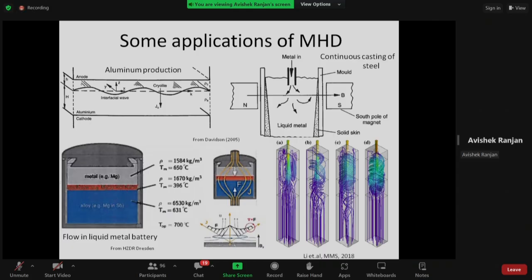We have that in our department here, and we have been using it, not for liquid metals yet, but we plan to use that. But the difficult thing about that is it only gives you the velocity on a particular line. So it works like the LDV, laser Doppler velocimeter, in the same way, but here it uses sound waves. Now sound waves can travel in opaque liquids also, and so they travel, they reflect back, and the shift, the phase shift, is what is recorded and converted to velocity. But the limitation is it only gives us the velocity in a particular line.